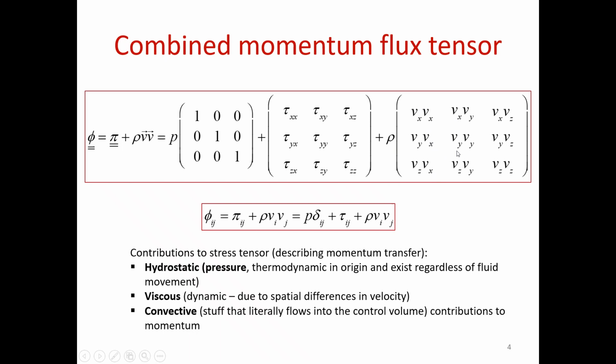And then here we have that same rho V, multiplied by Vy. That's what flows in across the Y plane, and then across the Z plane. So again, I have to have a tensor describing all of these. So component-wise, it's actually easy then to write this down. It's really rho Vi Vj, where ij is my combination that I'm looking at.